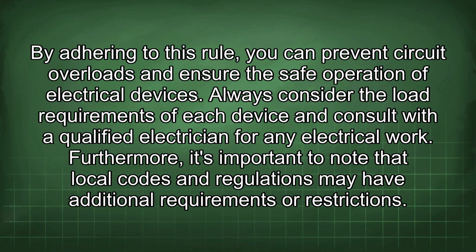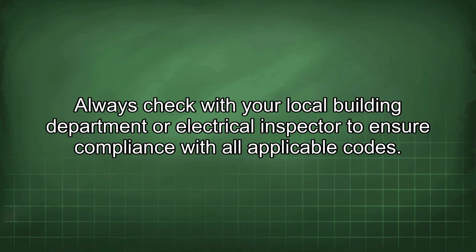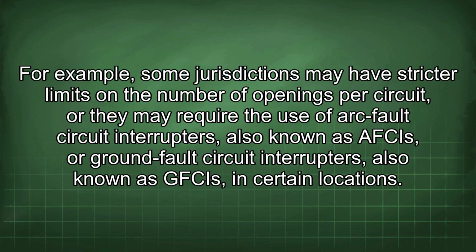Furthermore, it's important to note that local codes and regulations may have additional requirements or restrictions. Always check with your local building department or electrical inspector to ensure compliance with all applicable codes. For example, some jurisdictions may have stricter limits on the number of openings per circuit, or they may require the use of arc fault circuit interrupters, also known as AFCIs, or ground fault circuit interrupters, also known as GFCIs, in